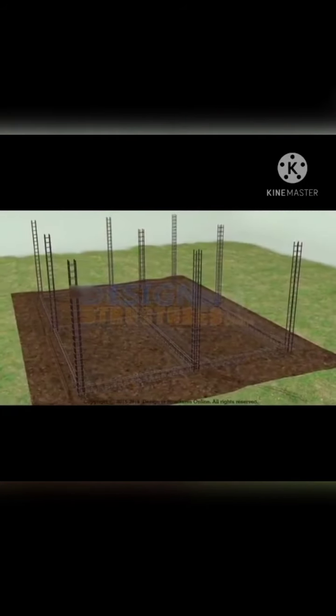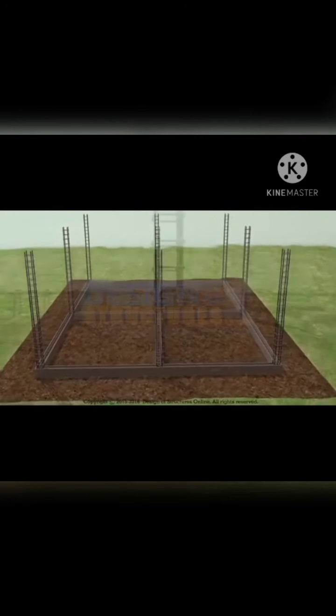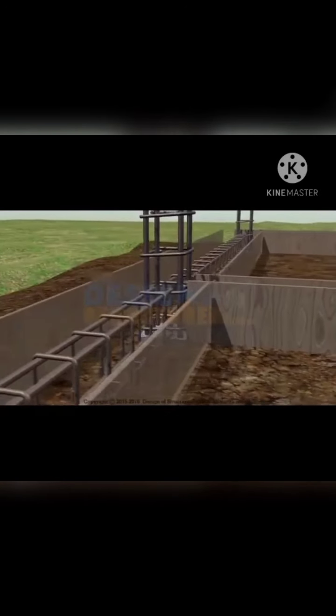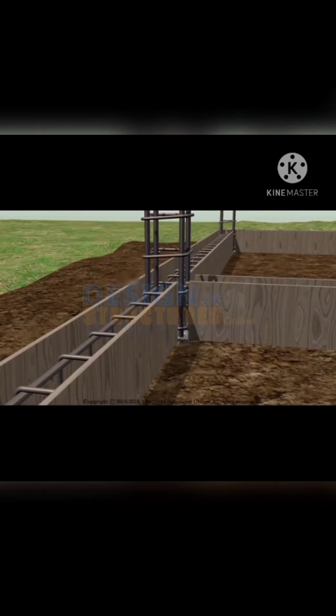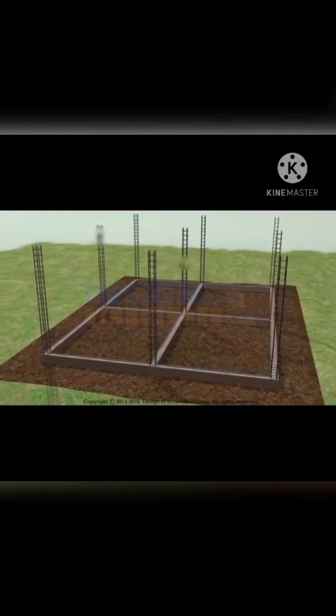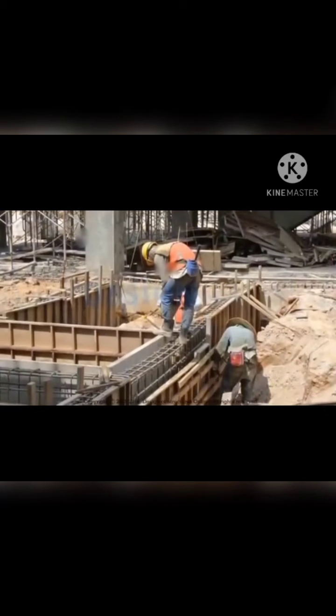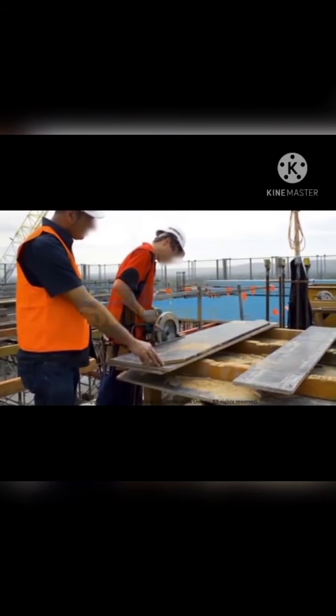Joints in the beam shuttering should be tight against leakage of cement grout. Construction of shuttering should permit removal of various parts in desired sequences without damage to the concrete. Beam concreting. Beam is poured with concrete with grade mentioned in the drawings. The positioning of reinforcement should be properly aligned. Shuttering parts and connections should be arranged in a way that makes formwork removal easy and simple, prevents damage to concrete and formwork panels so that it can be reused without extensive repair.